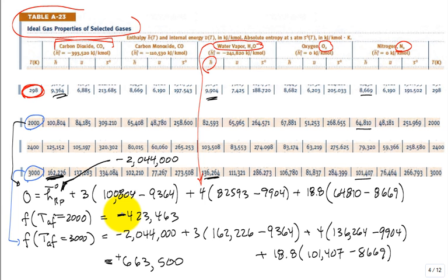So when you interpolate, you get a better estimate of the adiabatic flame temperature. It's 2390 Kelvin. Shoot for a value that you might think is ridiculously low, 2,000. Shoot for a value that's ridiculously high, 3,000. Usually you bracket, interpolate. Even if you don't bracket, you can still interpolate. It's called extrapolate outside of the range. It's still going to be very accurate.